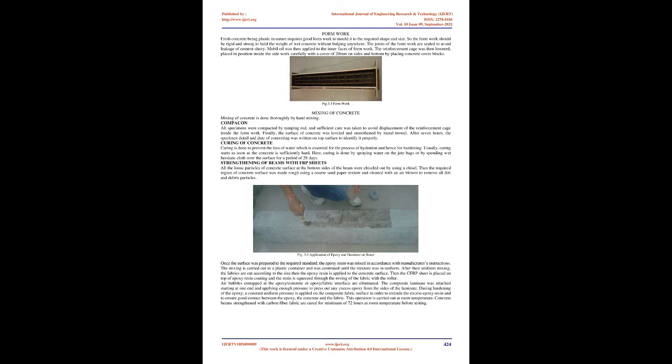Applied to reinforced concrete structures for flexure, CFRP typically has a large impact on strength, doubling or more the strength of the section is not uncommon, but only a moderate increase in stiffness, perhaps a 10% increase. This is because the material used in this application is typically very strong, e.g., 3000 MPa ultimate tensile strength, more than 10 times mild steel, but not particularly stiff, 150 to 250 GPa, a little less than steel, is typical.